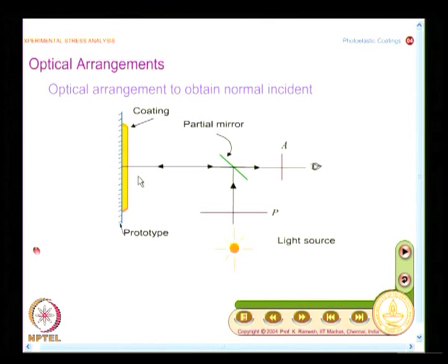And what strikes you first? We looked at, in the case of transmission photoelasticity, thickness of the model is a key parameter. Then we modified it when we moved on to 3-dimensional photoelasticity, we looked at the length of the light path, because depending on the size of the 3-dimensional model and the angle of incidence, I may have different lengths.